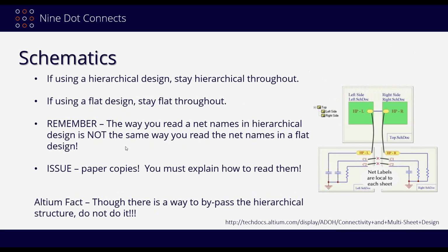All right, let's take a look at schematics over here. The schematic concept: there's a new concept that has become more and more prevalent. When I started in the industry, there were two different methods. You did global or you did flat, and we always told people to stay away from global because it just got too difficult to track things. The idea behind a flat design was that whatever was done on the schematic sheet was only allowed to leave the schematic sheet to another schematic sheet if there was a port there to represent it between the two sheets.